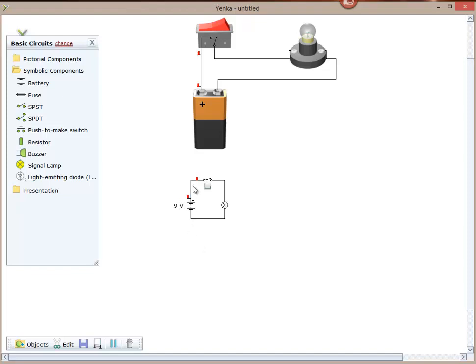So what's going to happen, we've got the potential energy of 9 volts available here. When the switch is open, no power is able to flow, despite the fact that there are connecting conductive wires. That gap effectively acts as a 100% insulator. No electrons are able to pass. When we close the switch, power is able to flow through the switch down to the filament bulb, and it's able to cause the light to light up.